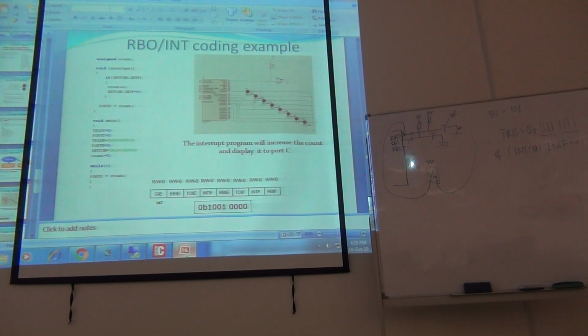Alright, so put back over there. The command, you need to have it. You need to clear back the bit for the flag. Must put back. Then you can see that the interrupt does not happen continuously. It will wait for the input for RB0 and then the interrupt will happen again. Okay, understand?